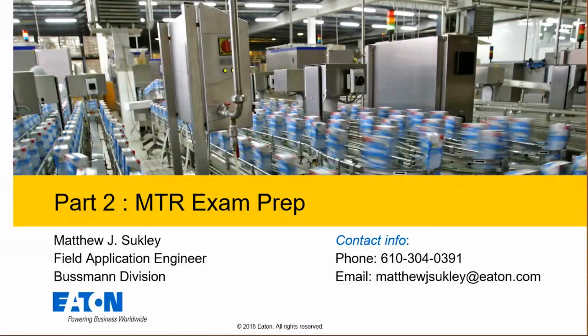This will be part 2 of the exam prep, about drives, fuse holders, distribution blocks, maybe some MMPs, as well as some contactors and overloads. When we're talking about overcurrent protective devices, these are your fuses and your circuit breakers, and we are going off their interrupting ratings. They don't have an SCCR rating, they have an interrupting rating. So just be mindful of that. When we raise SCCRs, we're raising the ratings of components, and we're not raising interrupting ratings. So just want to make sure you're absolutely clear on that.